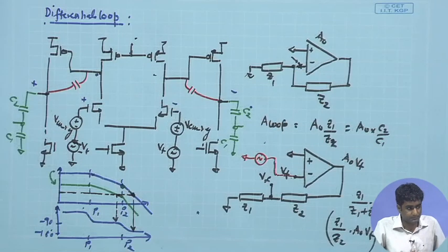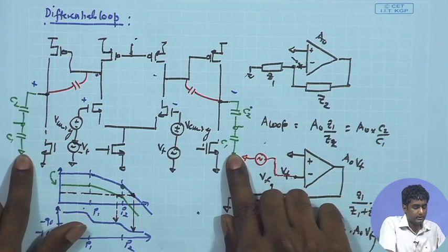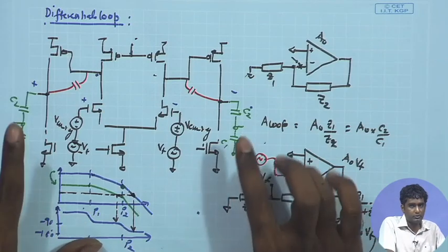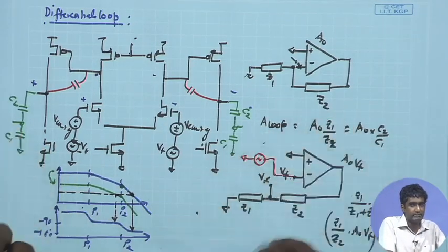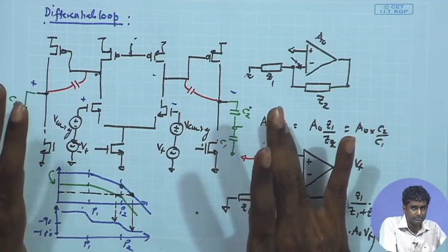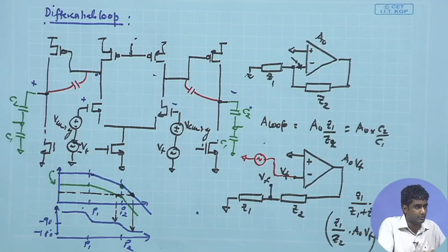operation. Sir, we need this capacitor C1 at ground or some DC potential? It will not matter much. The overall response will not matter much, because in the actual operation this is connected to the electrode, and you do not have much control over the DC potential over here. So, that is anyway decoupling the DC bias of the amplifier from any DC level that you may have at the electrode.